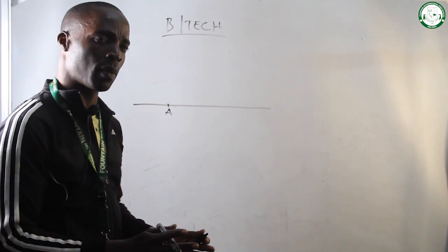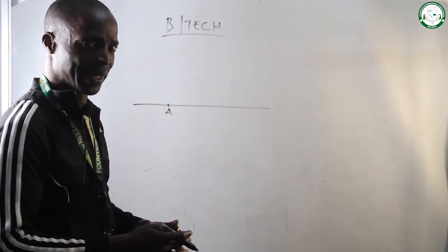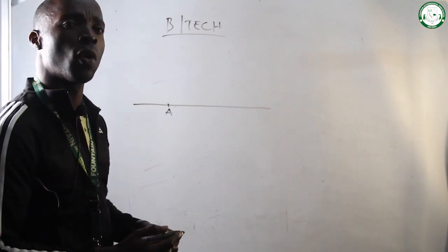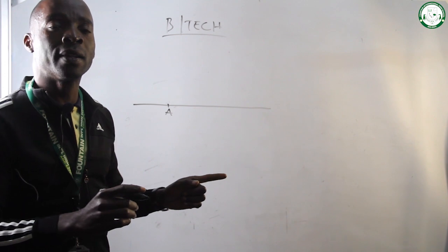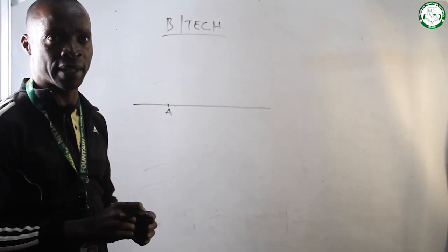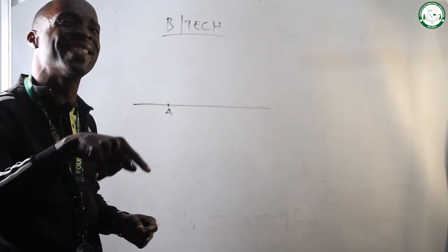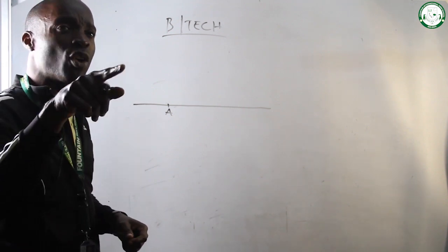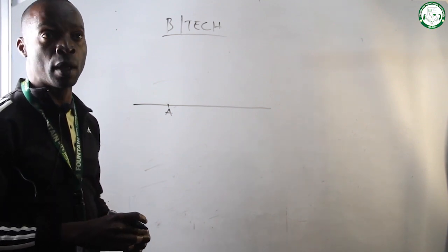This is my point A. From this very point, I can decide to measure out AB, and it's still all right to do that. Use your compass and measure out the diameter given to you for the circles, which is 60 millimeters. To draw a circle, you have to use the radius of that circle. Divide it by 2. So the radius of that particular circle is 30 millimeters.